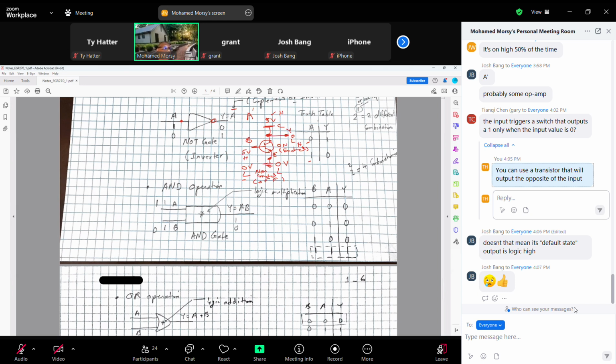Based on the operation of this AND gate, which is logic multiplication, we just multiply the 2 inputs. So 0 0 gives a 0 output, 1 0 is 0, 0 1 is 0, 1 1 is 1. Please, here I need every one of you. Tell me what you see here. What is the remarkable thing you can see in this truth table?